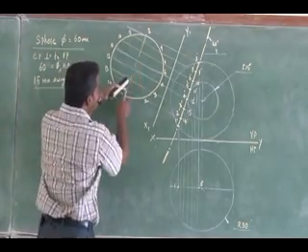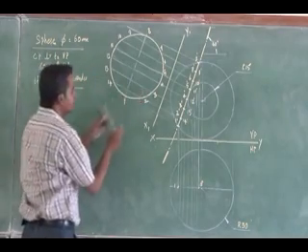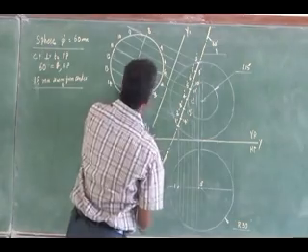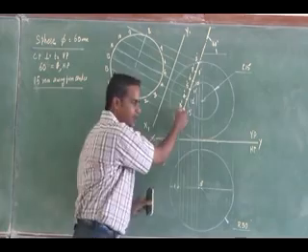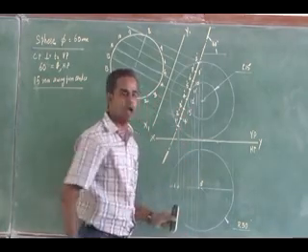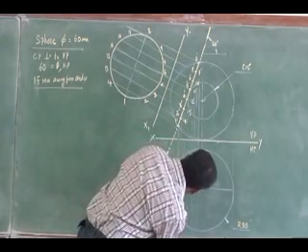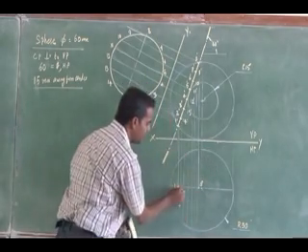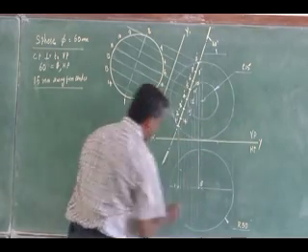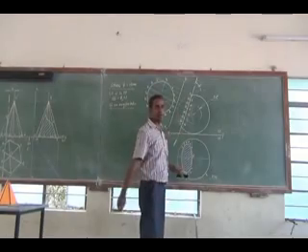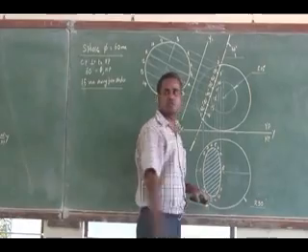So from the diametrical line, what is the distance for 2? That you measure. This distance I am measuring from the diametrical line. Similarly on the 2 and 14 projector line, which you have drawn to the top view, from the diametrical line, transfer that. Similarly from the bottom and the top, transfer that. So this is the true shape. Right? I have transferred. Then you can connect these cutting points with a smooth curve.